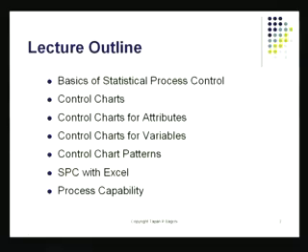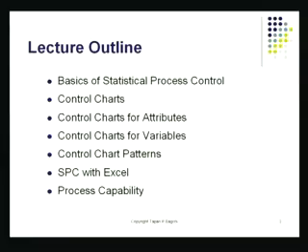Then we've got other types of quality characteristics where I can make a measurement. For example, the dimension, the length of this pen, or some dimension of the roundness of the tip, for example, those can be measured. And again, those measurements can lead to a set of control charts which are called variables control charts. You might have heard of the charts called X bar chart and range chart, R charts, and so on. Those come under what we call variables control charts. And charts like the P chart and the C chart and the U chart and so on, those come in the category of attribute charts.